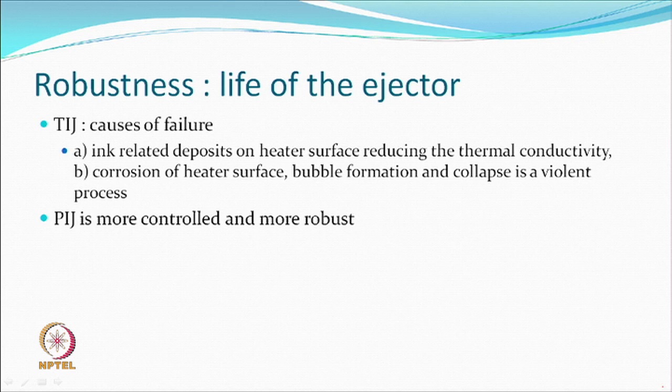But that is part of the thing, it is understood something will happen. If that is the only reason, you will still be okay, because once something is deposited, thermal conductivity changes. Other is the corrosion of the heater surface, bubble formation and collapse, etc. They can also cause failure of the head, and so you may require replacement.